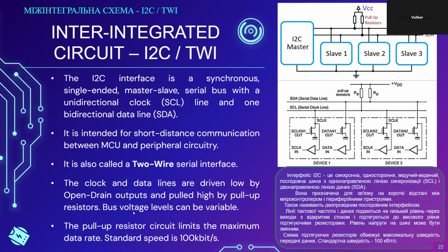It's using an open drain transceiver, open drain output circuit, which means it has one dominant state, which in this case is driving to ground, driving to zero. And it has a recessive state for 1, which is being pulled up with resistors. There's a number of characteristics that are defining the I2C bus because of this.